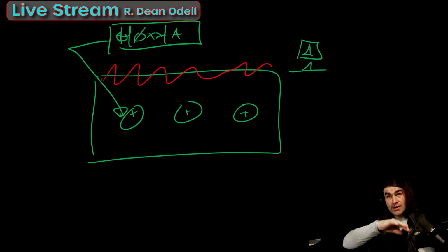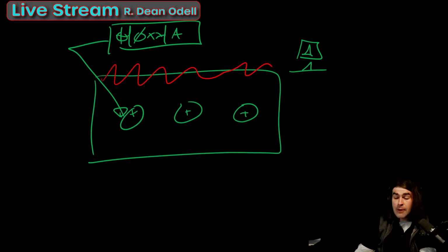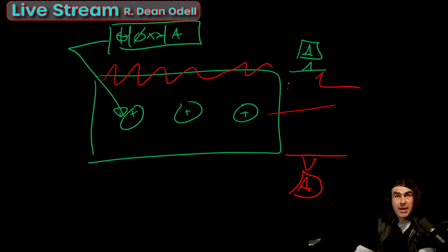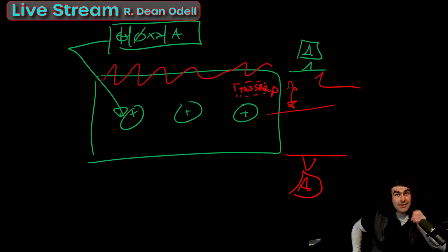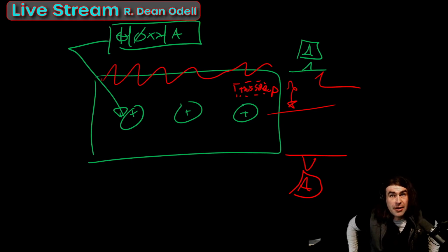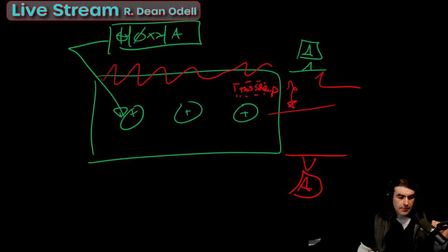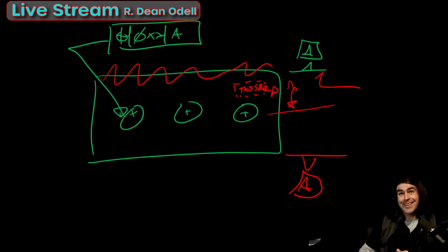Maybe it's just convex and it's rocking. We can't move it over here, right? Because this is what the designer, and I know this part looks symmetric, but say they put an ident mark here, right? This side up, right? Whatever it is. I would assume you would need some kind of paperwork to move the datum. That would be my opinion. I wouldn't move it unless I had some kind of written, express, CYA documentation for that.